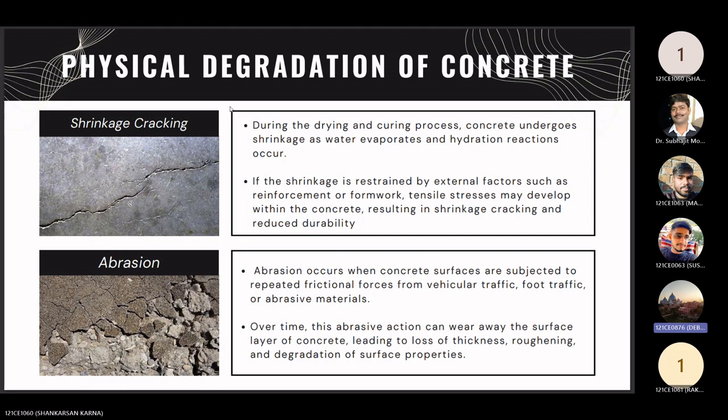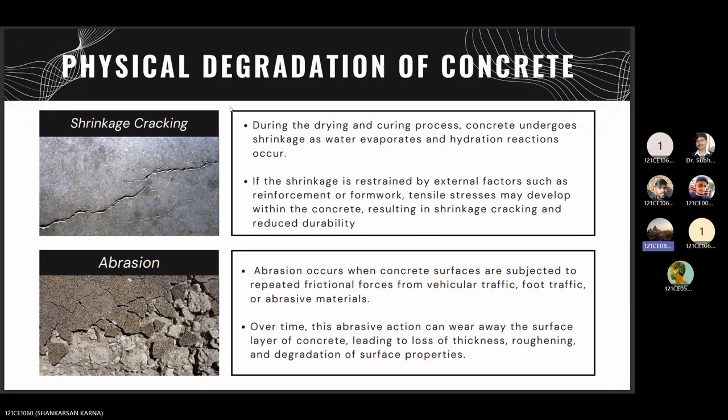Abrasion. It occurs when the surface layer of concrete is subjected to abrasive force or repeated friction, such as vehicular traffic, footpaths, or other abrasive material. In due course of time, the surface layer of concrete wears down, leading to loss of thickness, roughening, and degradation of surface properties.